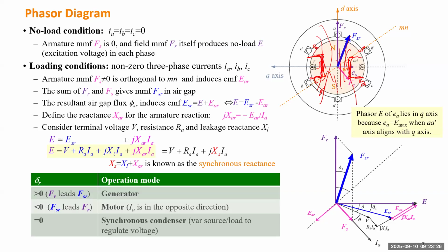So we are familiar with this formula in the electric circuit: the voltage is equal to current multiplied by resistance, right? So if you have a higher resistance, the current will be smaller. The analogy in the magnetic field is the magnetomotive force, which is similar to electric voltage, and it is equal to flux multiplied by also R. The R usually we give a subscript M to distinguish it from electric R. We call Rm the reluctance.